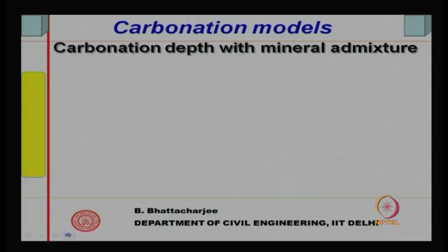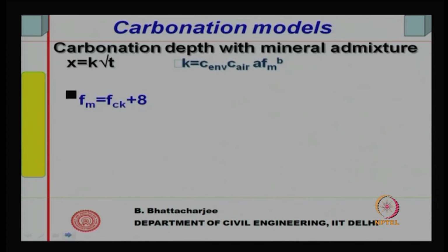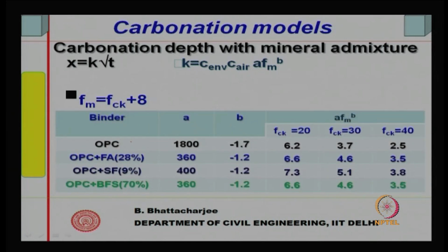Well, one more durability aspect related to the corrosion process is carbonation depth with mineral admixture. This depends upon alkalinity, calcium hydroxide. If calcium hydroxide is consumed by the atmospheric carbon dioxide, the pH of concrete reduces, and that is carbonation. So, it has been observed that if you use OPC